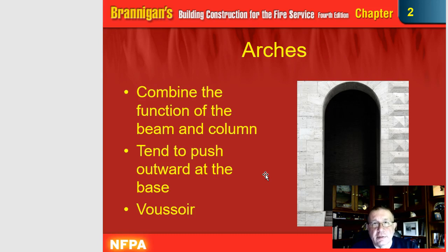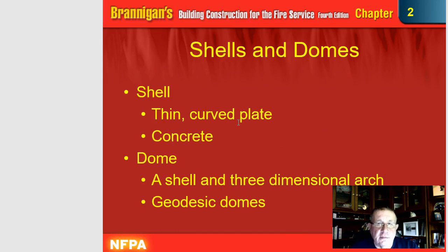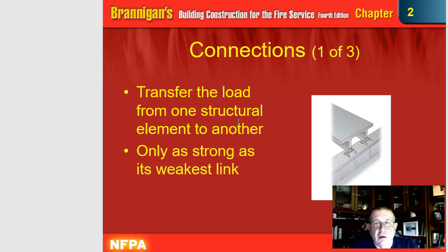We're seeing a lot of arches in buildings again. Arches are very great, but the problem is, look how they're built. In most cases, arch is formed and material is basically put around the arch. If it's concrete, it's plastered over it. They don't bring in a concrete arch unless it's molded or cast in place. So that means they have to build the jig, as they call it, and put the frame together and put the arch and pour it in concrete. Then they place it in the building. Rigid frames, hard shells and domes, these are all important.